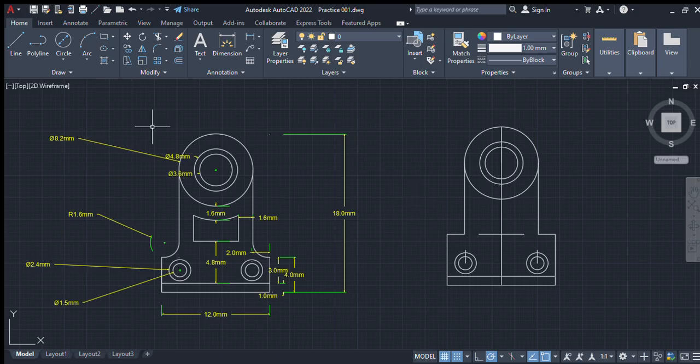So don't stress yourself. Go to fillet, this fillet here. Press here, it will tell you to press radius. Press radius, enter. So after radius, enter. Put your 1.6 there. Enter. You see? So press enter again. That will be here, here, enter. So you see, we have gotten our result.